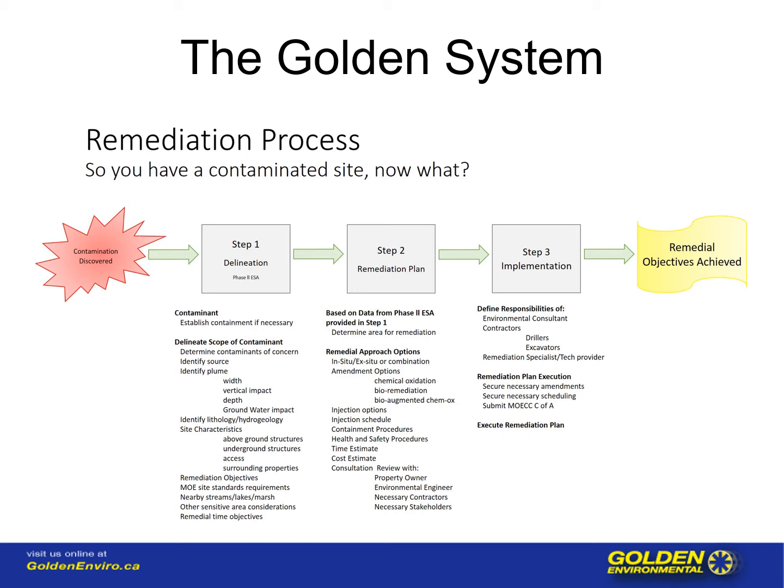Second of all, we need to deal with the source of the contaminant, often very tied into determining the contaminants of concern. Identifying a holding tank, an oil tank, storage drums, manufacturing processes which may leak contaminant.